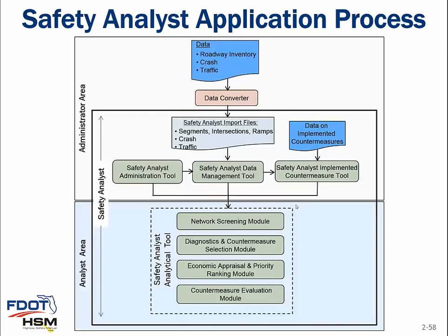This figure illustrates the Safety Analyst application process for Florida. It further provides the interactions and the data flow between the data converter and the different components of Safety Analyst. The only new component in this process and specific to Florida is the data converter. The data converter was developed to convert Florida data into the standard format required by Safety Analyst. The converter has the capability to generate all the required import files for segments, intersections, ramps, and their associated crash and traffic files. The output from the converter can be directly inputted into the Safety Analyst data management tool.